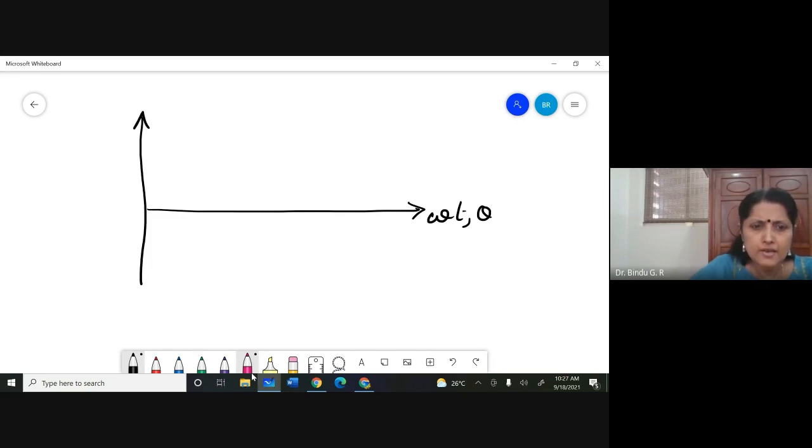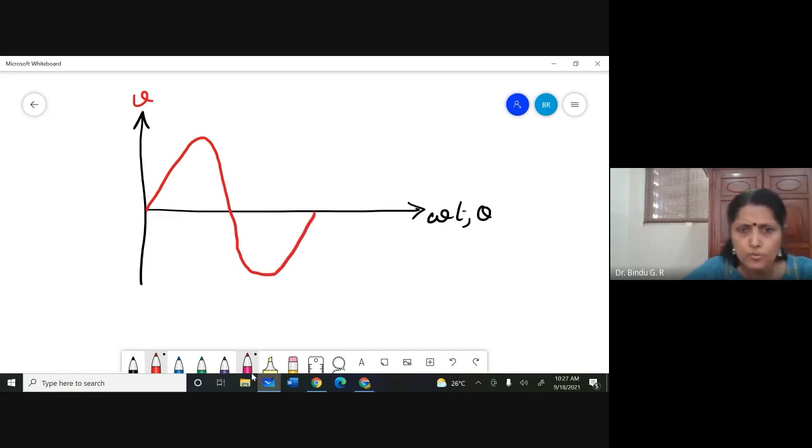And then if I draw the voltage like this, again I'm taking voltage as a reference. So, I'm drawing voltage here as V. I will be leading, isn't it? So I leading by pi by 2 means current I has already passed the 0 point pi by 2 before, which means the current now is coming like this and has passed through.